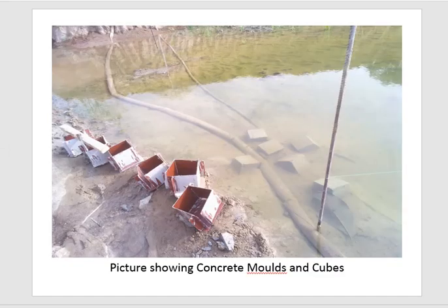I'm seizing the opportunity of a challenge at the site, a seepage problem at the site, a sump I created, I dumped those cubes there. So I've been able to do the concrete strength test, the crushing of cubes. You just have to take the cubes to the lab and crush them and be able to determine the strength of the concrete. Okay, so when you talk about materials like this, one of the things you need to also consider is the storage of the materials.